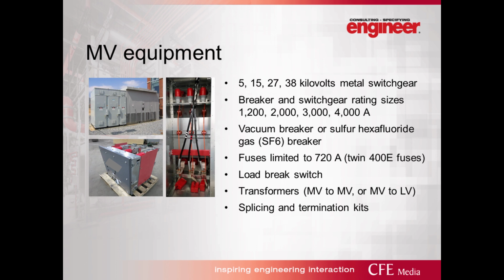In this instance, there are two. It was a data center that had a utility A and a utility B feed. So we brought a feeder from both of those to this transformer so it could be fed from either source should power go out at one of the other sources.